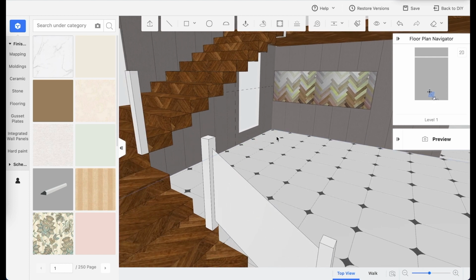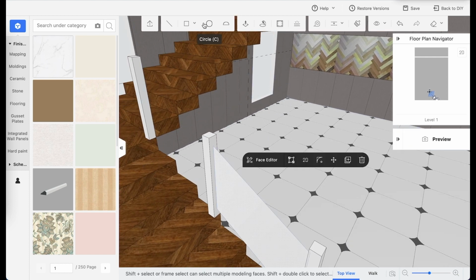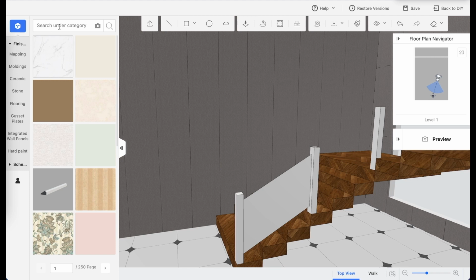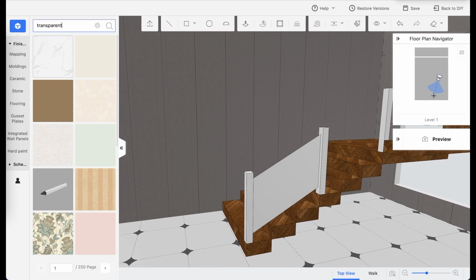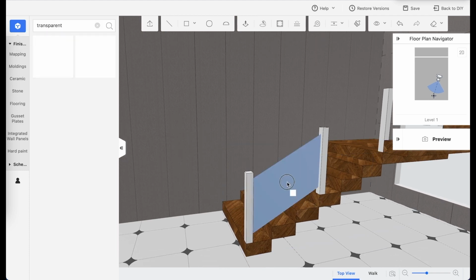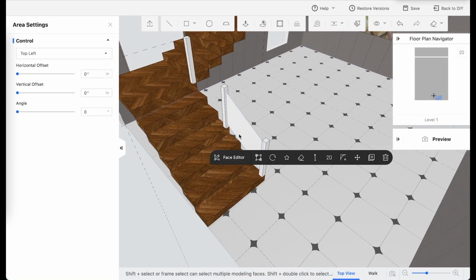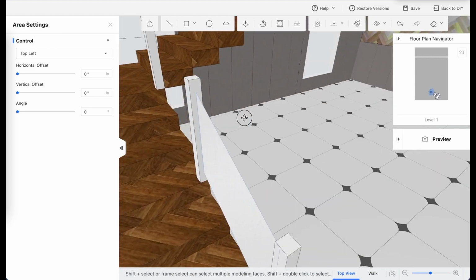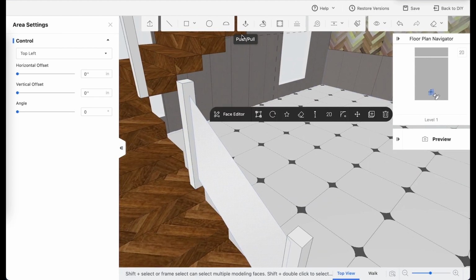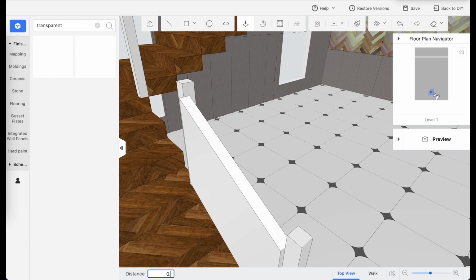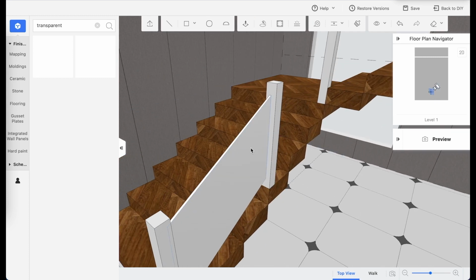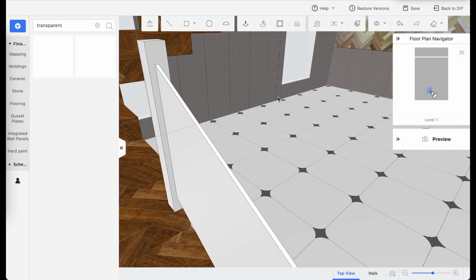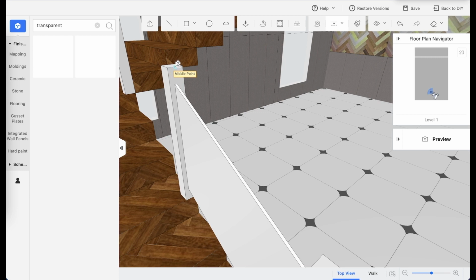But before we copy it, let me extrude it. You know what? I think the best way is to go to transparent material, apply it to both sides of the surface, and do an extrusion. Push and pull 0.5. Okay, there you go. Select this whole thing. Now you can group it, and then the next thing you can do is use a guideline to make sure that it is centered on the edge.